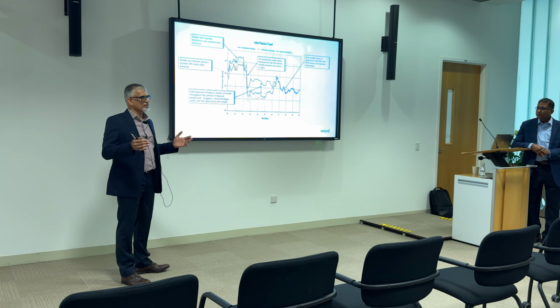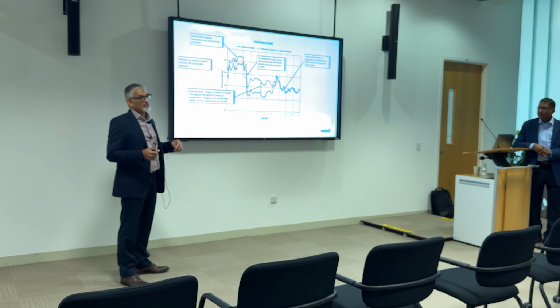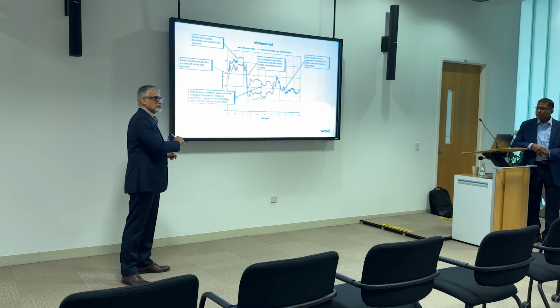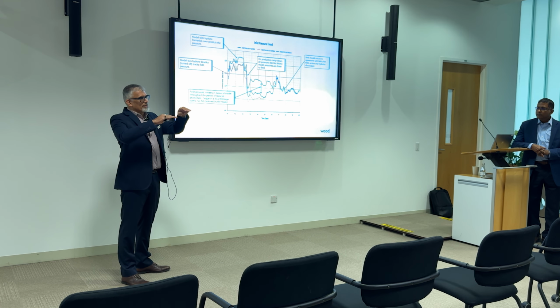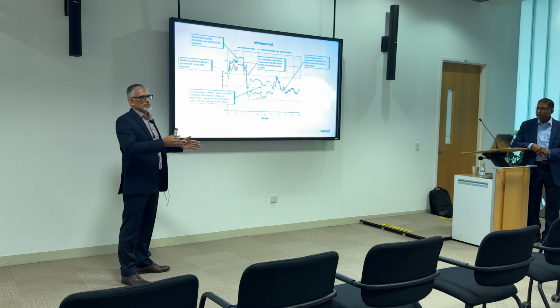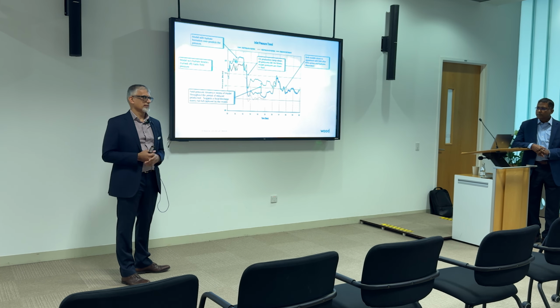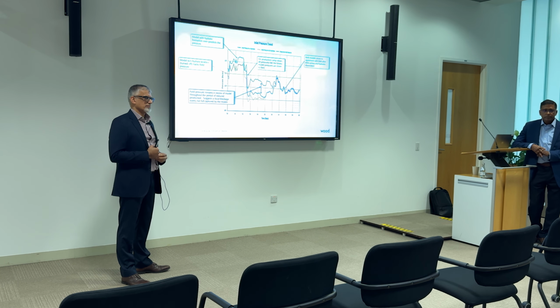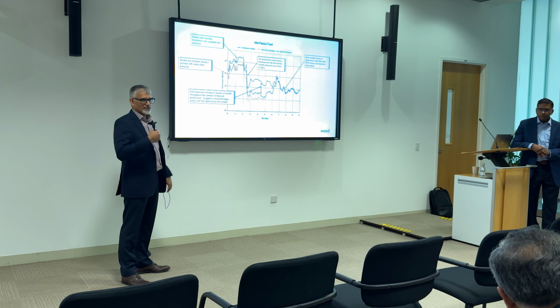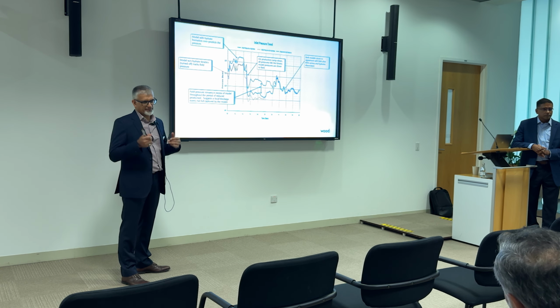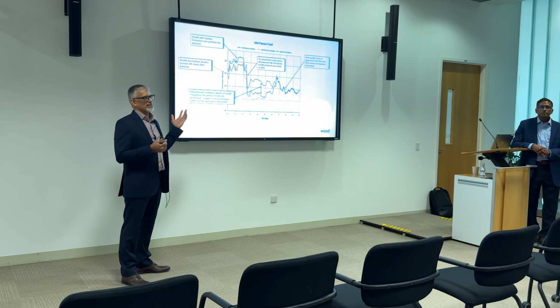Now suddenly they've gone up 3 or 4 degrees. So then you say, it could be water breakthrough. I'll tune the model. Do I match it again? Now, if you can match it over, say, 3 months, 6 months, 9 months, then you say, no, I've got it under control again. So yeah, this is a long-term online system, and systems like these have been running for 20 years or so.